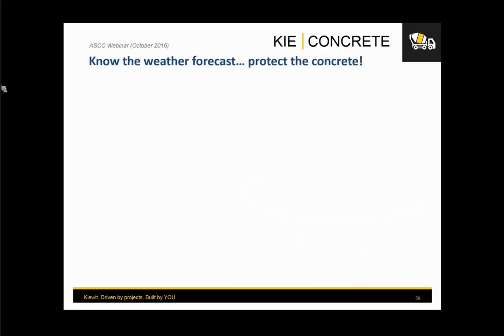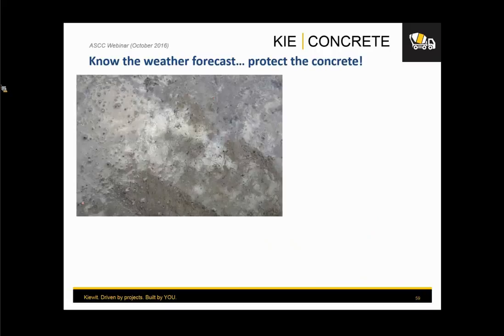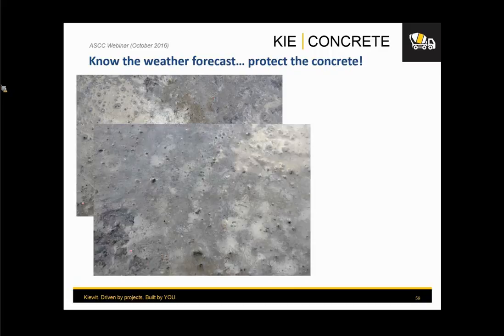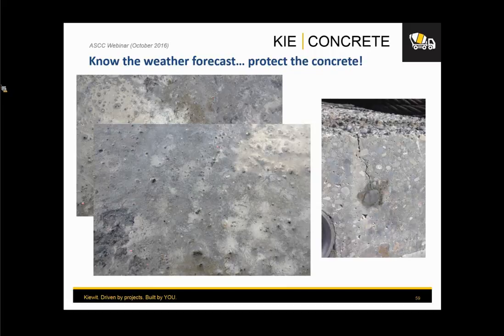The next one is the one where I'm telling you to know the weather forecast, and this is a very, very controversial case where we allowed the concrete to freeze. And as you can see, that goes back to the basics, right? If you know your weather forecast and you protect the concrete properly, you're not going to get into these issues. And it is true, concrete is going to freeze if you allow it to freeze. Here you have some photos where you can see the crystal growth on the top of the surfaces, and on the sidelines we also allowed some settlement of the concrete over the rebar, and settlement cracking showed up too. We had to remove and replace the entire slab that we allowed to freeze. You don't want to go through that, so make sure that you know your weather forecast.